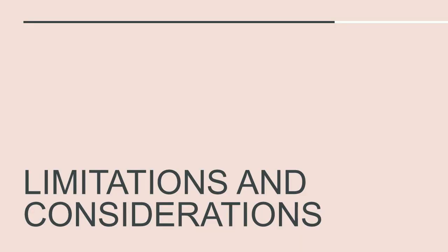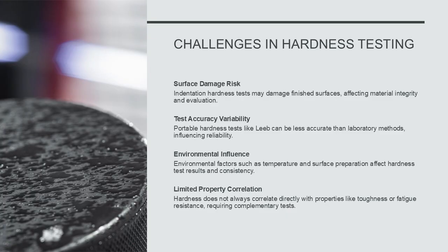Challenges in hardness testing. Hardness testing has limitations and considerations. Despite its usefulness, hardness testing has limitations. Indentation tests can damage finished surfaces and may not represent bulk properties for heterogeneous materials. Portable tests like Leeb may be less accurate than laboratory methods.